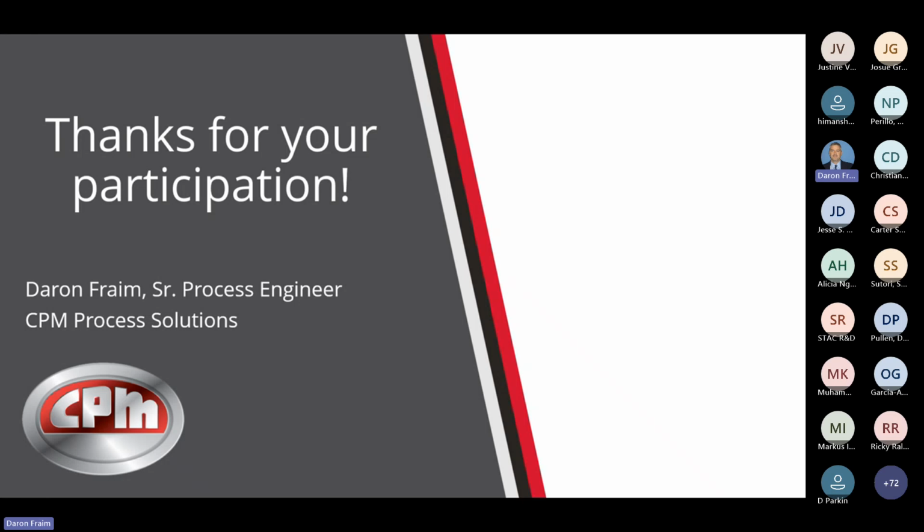Typically it really depends on the application. When you're dealing with glass filled, silica, highly abrasive material, that usually requires a higher abrasion resistant metallurgy. When you're dealing with corrosion, it changes a little bit. We offer metallurgy for all types of applications, geared more for abrasive versus corrosive, or both.